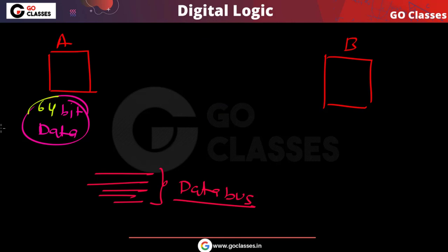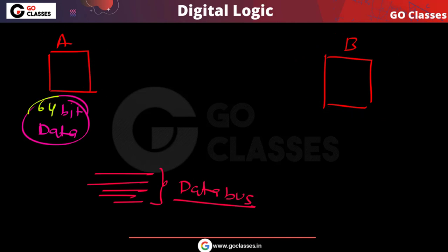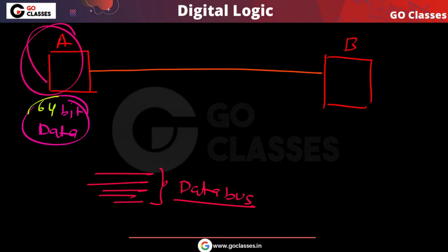Because device to device communication, from one device to another, is done in serial manner. What it means is that from this computer to this computer we have a single wire. Now what should you do? Inside your computer you have data in parallel. This 64-bit data you are receiving in parallel, but you want to transfer this data on this single wire. Because this is a single wire, on this single wire you have to do serial communication.